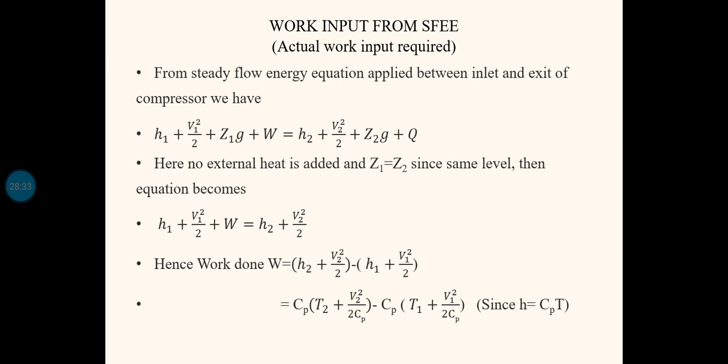So h plus kinetic energy means half mv square. For unit mass it is v square by 2. So h plus v square by 2 will be the total energy of the flowing fluid if heat and all is not considered. So in that term, if a flowing fluid is isentropically decelerated to zero velocity, then the final state is known as the stagnation condition.